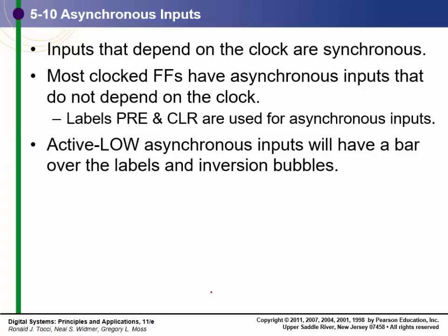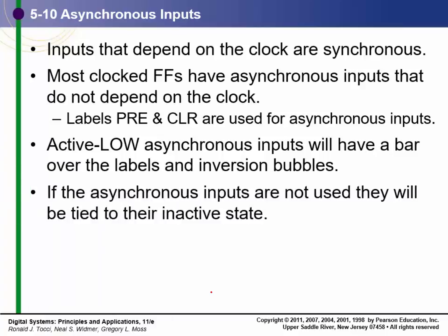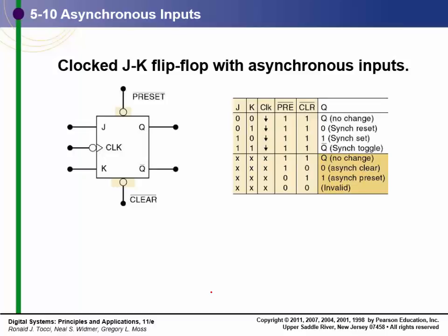They're active low. Asynchronous inputs have a bar over the labels and inversion bubbles. That's all that they are. If asynchronous inputs are not used, they're tied to their inactive state. In other words, most asynchronous inputs are going to be active low. Most are active low.